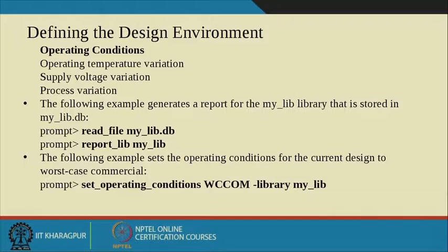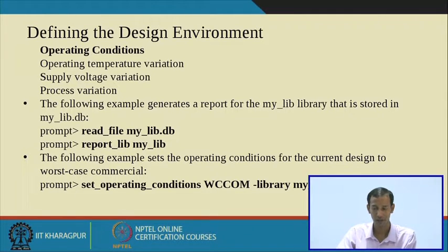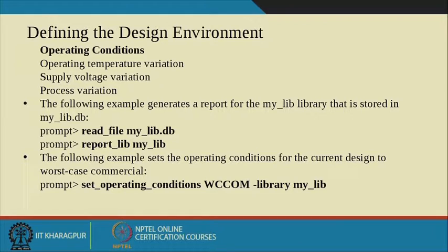After that, how can you define the design environment? Design environment means operating condition, which I have to set. How can you set the operating condition? By putting this command: set_operating_conditions with WCCOM -library, where the library name is my_lib, and WCCOM indicates this is the worst case condition. BCCOM indicates this is the best case condition.